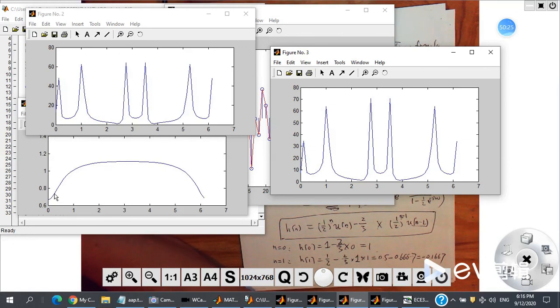but for low frequency, it is this part. The value here is small. That means we multiply this small number on this peak, and we get this peak. So here should be around 50, right? After multiplying by this value, which should be like 0.6 or something, 50 times 0.6, you get 30 something. This is around 30 something. So input in the frequency domain times the frequency response gives you the frequency domain of the output. And if you perform the inverse Fourier transform of these, you can have the time domain output.